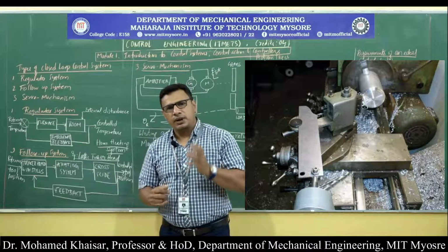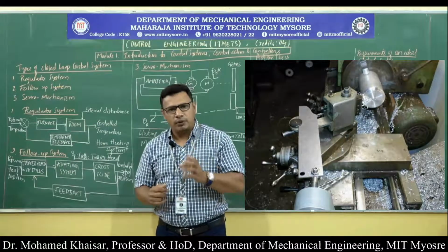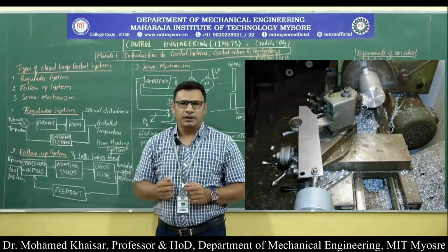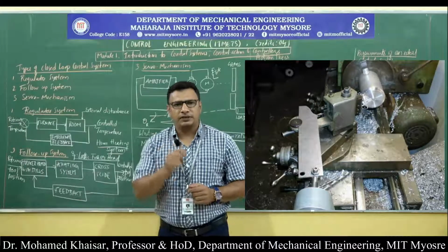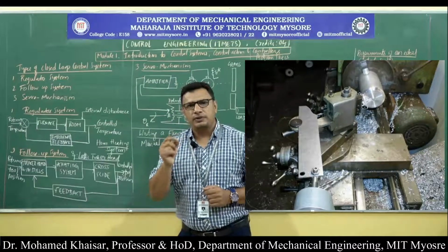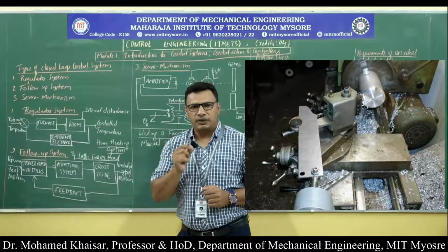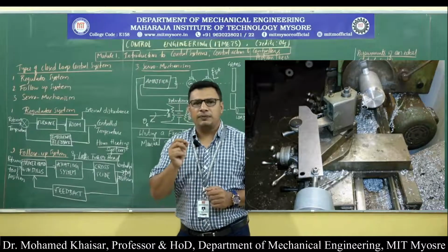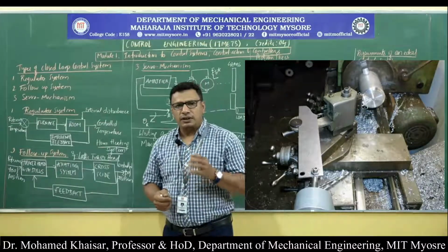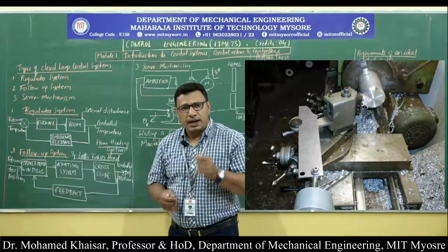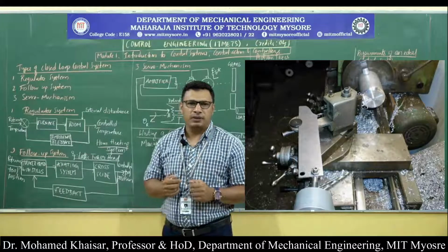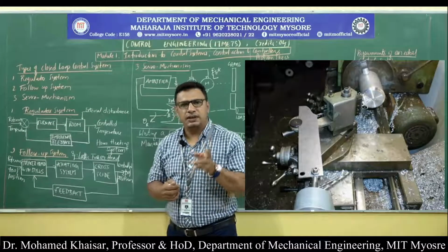right? The tracer head is one of the attachments that will be mounted onto the movement of the single point cutting tool of the lathe. This attachment, the tracer head, will be cut into a shape which resembles exactly the path of the single point cutting tool travel over the workpiece. Since the single point cutting tool of the lathe has to trace the path to which the tracer head has been cut, we call it the lathe tracer head mechanism.